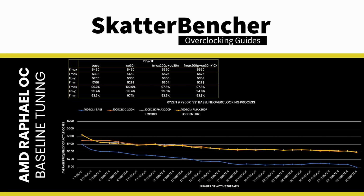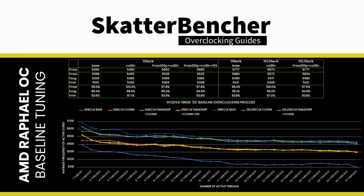In the next step, I tried exploring the overclocking headroom provided by the asynchronous E-clock. For each of the 3 variations, base, Curve Optimizer, and Fmax, I tried to find the maximum stable E-clock. For the base case, that's 106 MHz, for the curve optimized case, that's 102.25 MHz, and for the Fmax offset case, that's also 102.25 MHz. The base case with maximum E-clock provides both the highest maximum frequency and highest average frequency. It is matched by the Fmax offset case in minimum frequency.